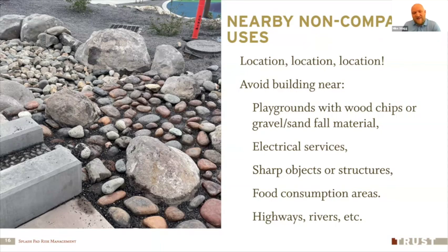You don't want the sand and the gravel getting into your recirculation system and fouling your pumps, and gunking up your filters. Okay, avoid playgrounds with wood chips and things like that. Look around for the electrical services. Where is the electrical coming in? Do you have a breaker box or big electrical boxes around? No, we don't want to build by those things.